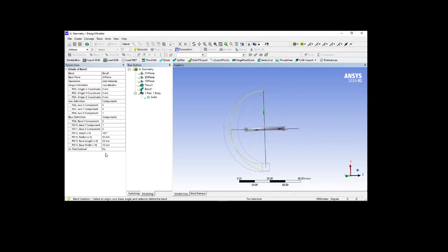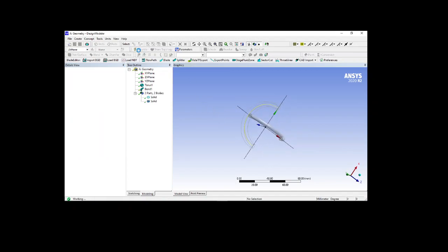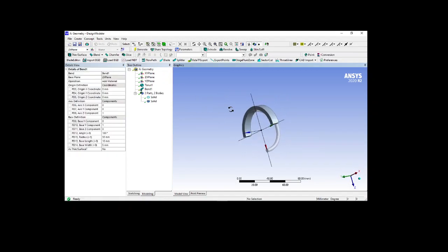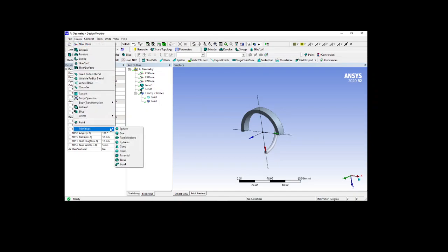And if you want to create a thin surface, and if you want to vary the radius, not only this is of 30, I want only 10. Okay, so I want only 5. That's it, the thickness is only 5. Okay, by the generate button I am able to create this geometry. Okay, so this is how I completed the primitive section.